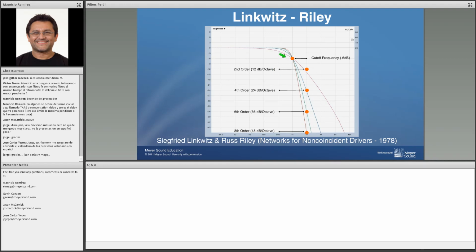And as we will see in the next presentation in July, having -6 dB offers a very nice advantage, because if you have a high pass and a low pass and cross them at -6 and you do phase align, the combination of these two filters will go flat. So this is the filter that theoretically can produce the flattest response without using EQ. And you can see that the Linkwitz-Riley is producing the attenuation that we expect, 1 octave later, or 2 octaves later, or 3 octaves later.